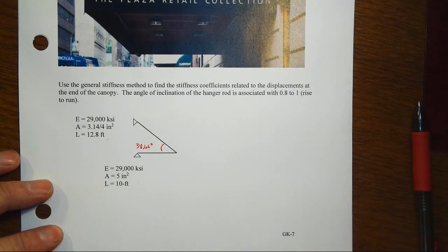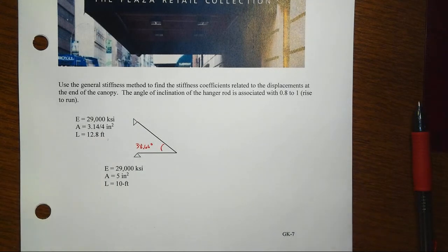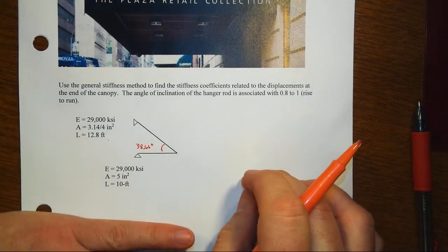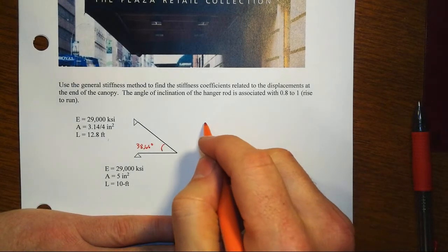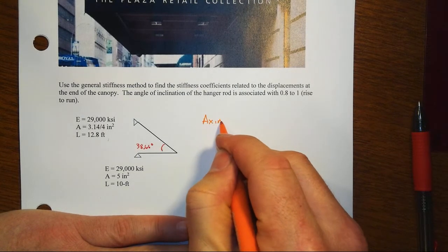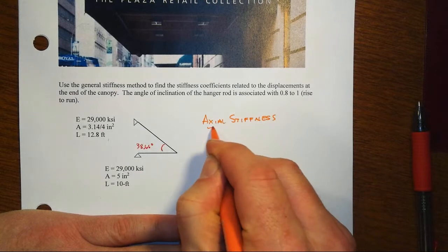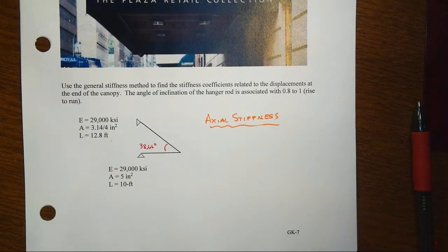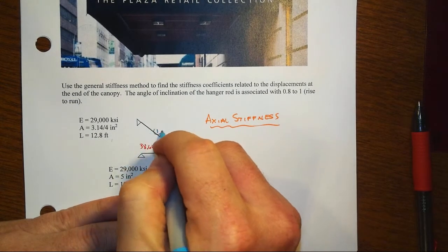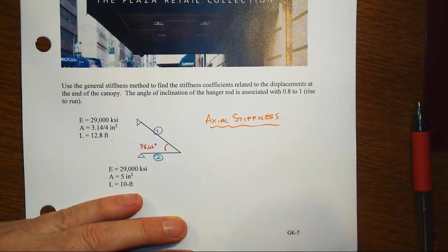Now, because we're looking at stiffness and we're talking about trusses, that means two-force members, and so the stiffness that we're really going to be interested in is the axial stiffness. I'm going to look ahead and do a couple of real quick numerical calcs so that some work later on will be a little bit easier. So this will be member 1, that will be member 2.